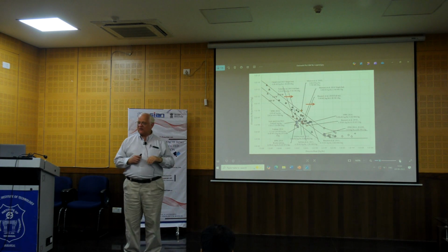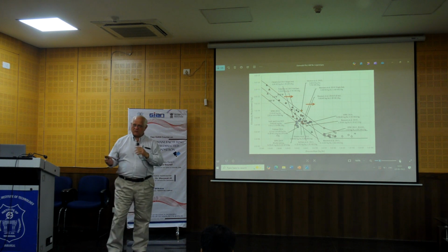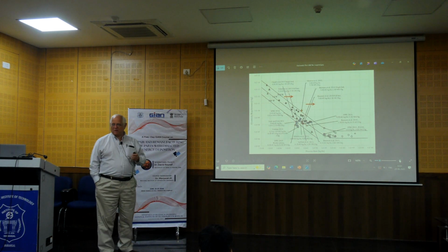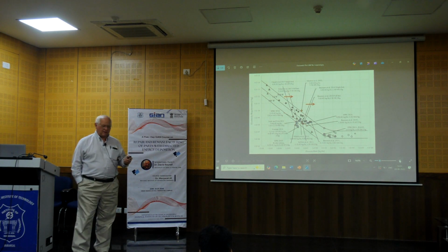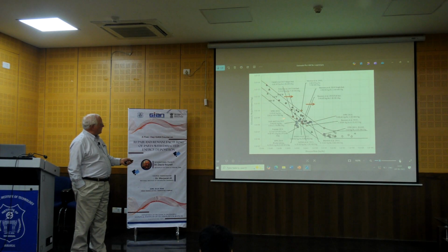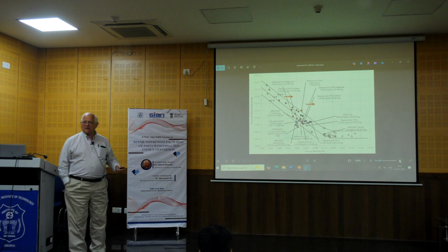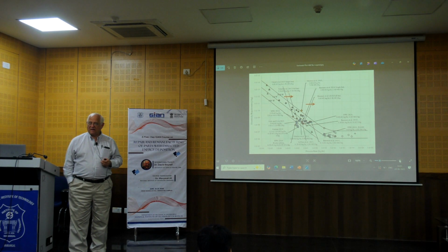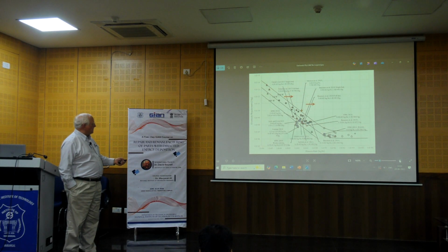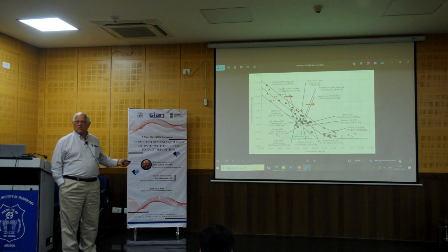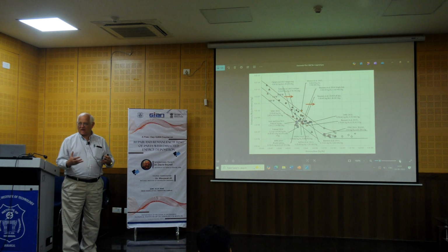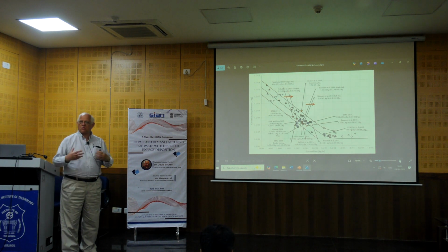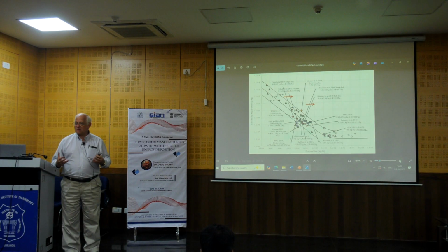I have two versions of the Gutowski plot here. I thought we could talk about that before we jump into mechanical properties in DED. So what this plot shows, and I think we touch on it again in a later lecture, is that each symbol represents a manufacturing process. And what Gutowski has observed is that the amount of energy required to complete that manufacturing process depends on how fast we can create parts using the process.